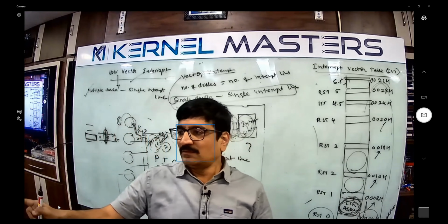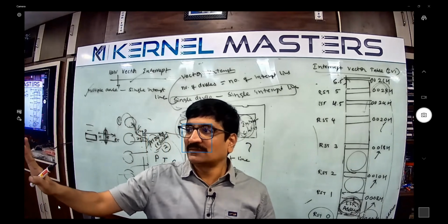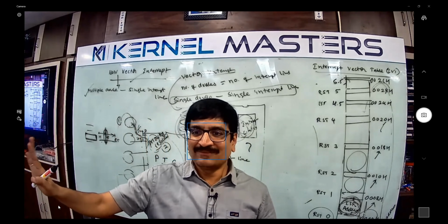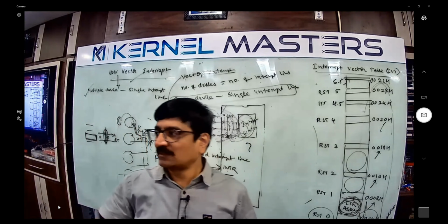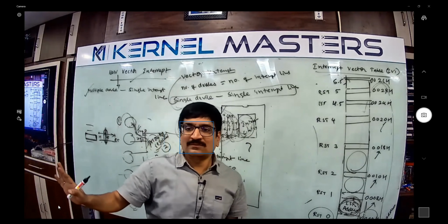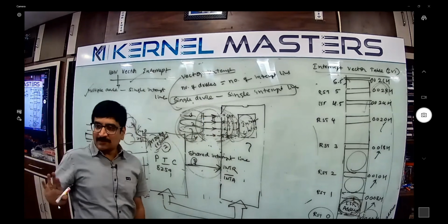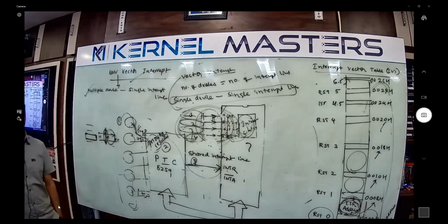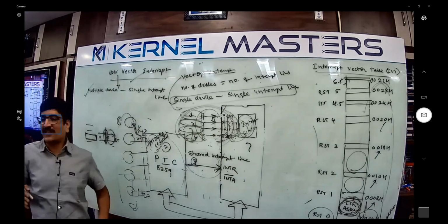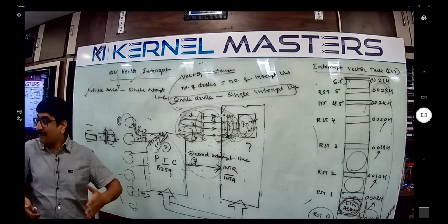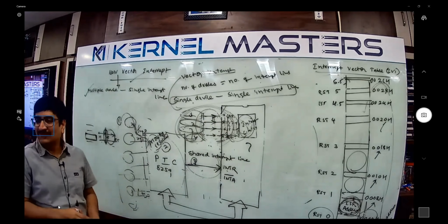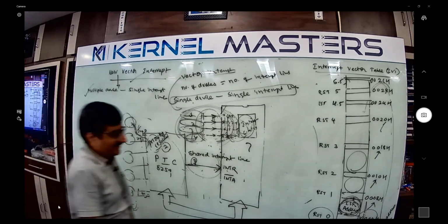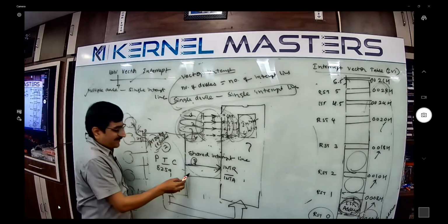Take MOV A, B. It takes a minimum of 4 cycles, compulsory. Nobody can stop it in the middle. The interrupt occurs and is acceptable, but it can be handled only after completion of the remaining 4 cycles. Then the microprocessor can say, now I am ready to handle the interrupt. Whenever the microprocessor is ready, it gives the what?